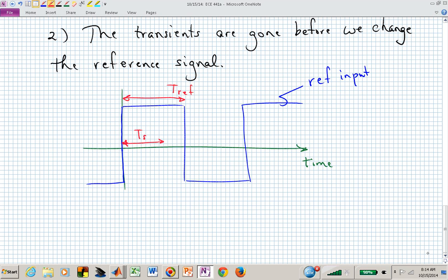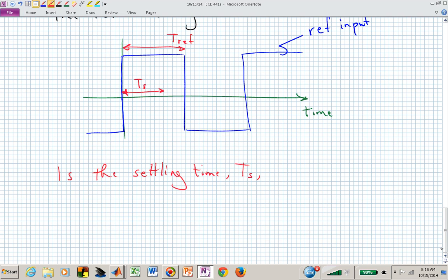then the second assumption is saying, or we need to ask the question, is the settling time T sub s? And you could find that by looking at your dominant poles and finding 4 tau from those dominant poles, assuming that they dominate the response.